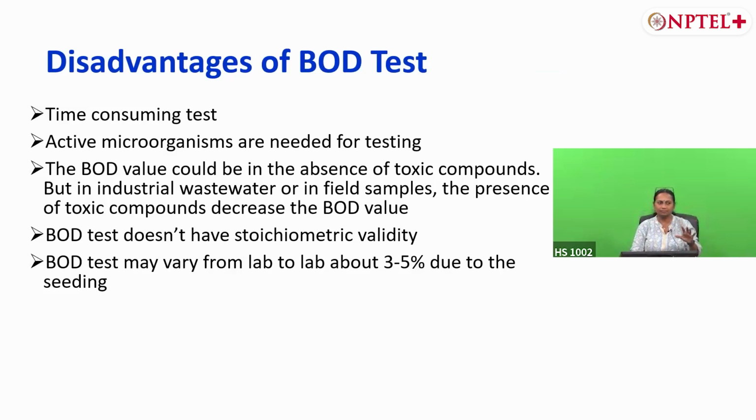No. Okay, clear? And when you fill the bottle, we have to be extremely careful. BOD bottle, I have some slides. It's a glass bottle, but make sure that when you fill the BOD bottle, there should not be any air bubble. If any air bubble is there, your entire experiment will be wrong. And when you put the cap, make sure that there is a water seal above the cap, so that even if some evaporation happens, no air will be entering into the BOD bottle. So these are all the precautions we have to take. Everything is there in the video. If anybody is interested, you can see that video.